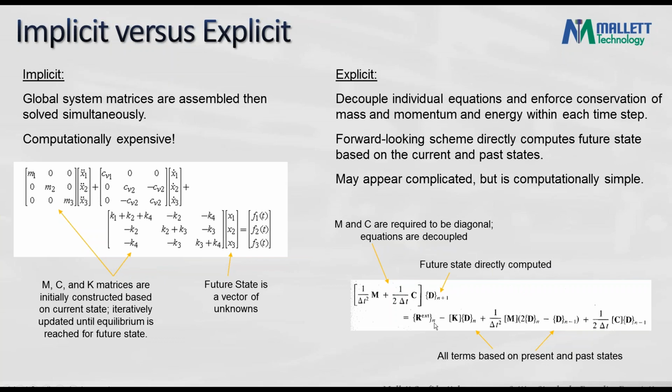But the other side of the equation, n minus 1, n minus 1. So these are past time points. Simply plugging in, we do have to compute element-level stiffness matrices. There's no way around that. But this is per degree of freedom. One by one, we can make this equation and boop, pop out what it's going to look like at the next time instant.